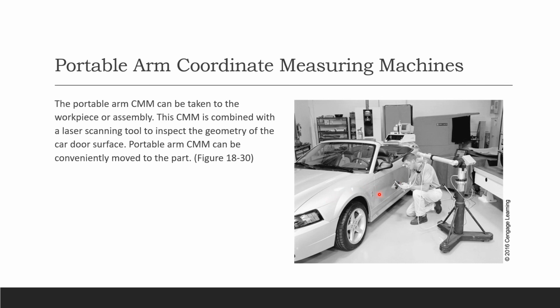What is this? What is this? A joke or something? So we want all the surface to be as where it's supposed to be. So you have edges right there, and you have the different profiles right here. Trying to decorate the car so consumers are going to love it. Yeah, so every detail needs to be inspected. So again, what are you doing with this inspection? You're checking if all these measurements are within the range, between your minus and your plus. Again, we call that tolerance zones.